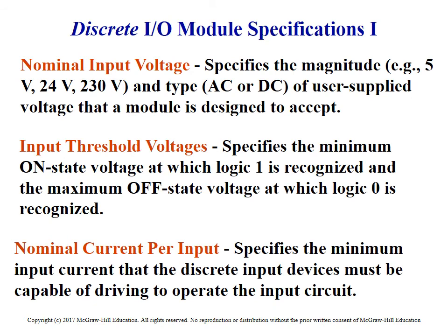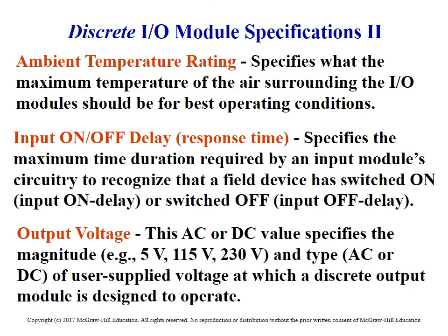Okay, I/O specifications. They're talking about the nominal input voltages and whatnot. They've got AC or DC. You're only going to be dealing with 24-volt DC, I'm very confident of that. Only in special applications, maybe some really old applications, you'll see something like a 110-volt input. When I first got into this business, there was such a thing as a 480-volt input, believe it or not. But everybody's kind of stepped away from that, and you're going to see something in the range of 24 volts for pretty much everything, inputs and outputs. The same thing with the output. You're going to see 24 volts DC.